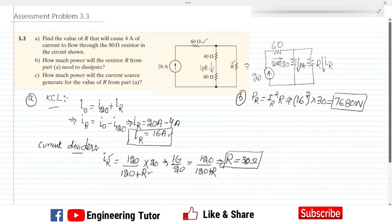How much power will the current source generate for the value of R from part A? How much power is it basically generating and passing to the overall circuit? In order to find this, we have to find the equivalent circuit here. Because we know this is the source, to find the power generated by the source, we have this formula: P is equal to IV. We know the value of I, but we don't know the value of V. So to find the value of V across it, we have to find the equivalent circuit.